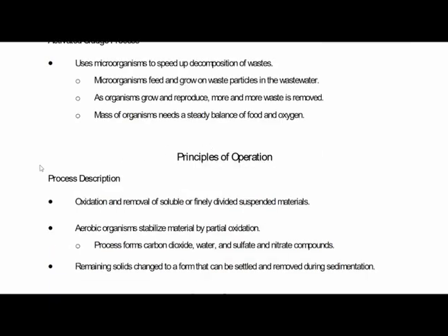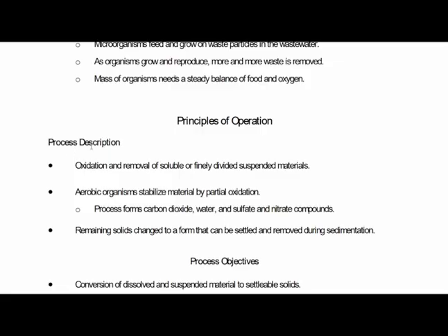Principles of operation. Process description. Oxidation and removal of soluble or finely divided suspended materials. Aerobic organisms stabilize material by partial oxidation. The process forms carbon dioxide, water, sulfate, and nitrate compounds. Remaining solids change to a form that can be settled and removed during sedimentation.